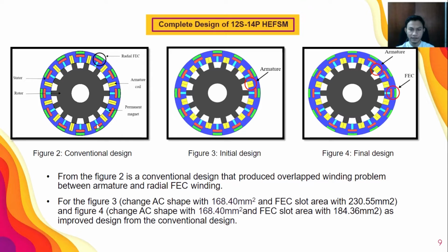For figure 3, I changed the armature shape to a slot area of 168.40 millimeter square, and the FEC slot area of 230.55, same as the conventional design.